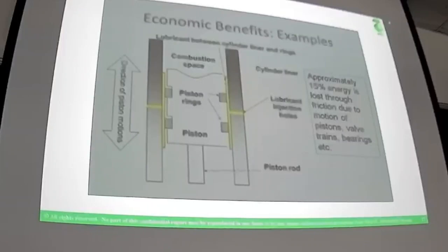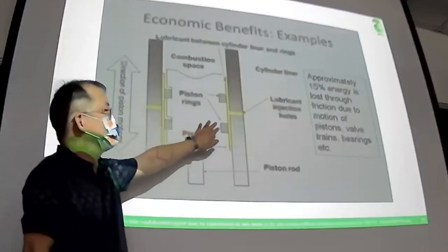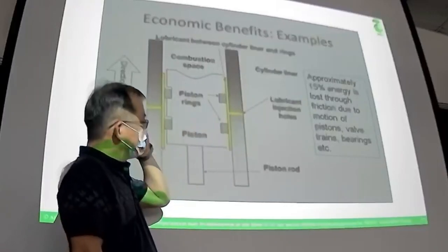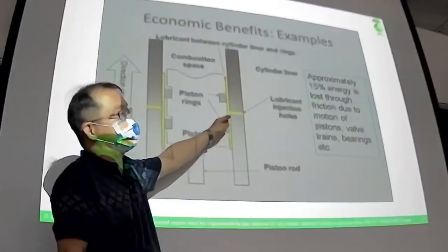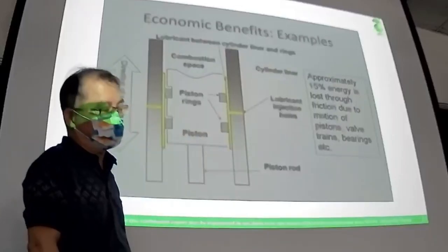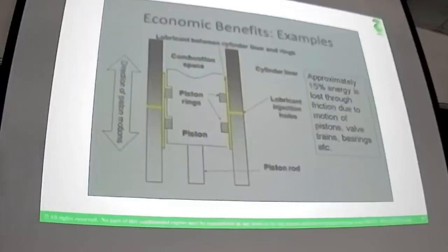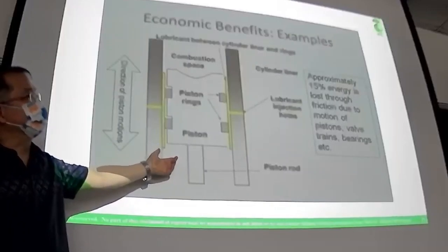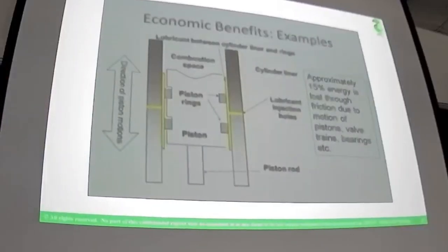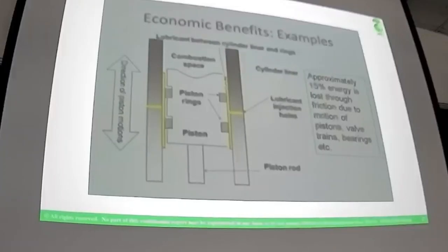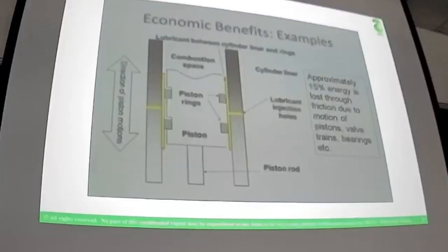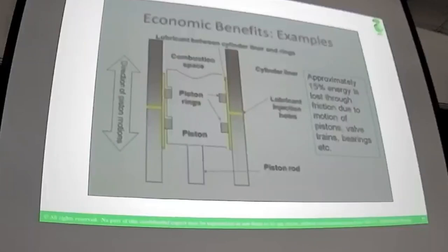For the lubricant used in the engine piston ring, it's necessary to add some high temperature additive, because inside the engine the temperature is more than 300 degrees Celsius, so you need to add some temperature resistant additive in your lubricant. We will mention this maybe in 2 months.